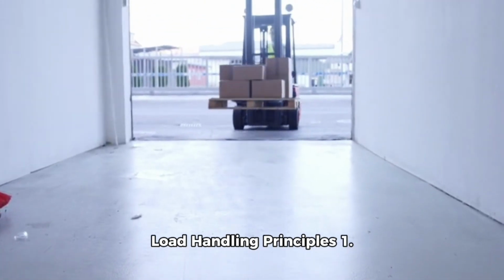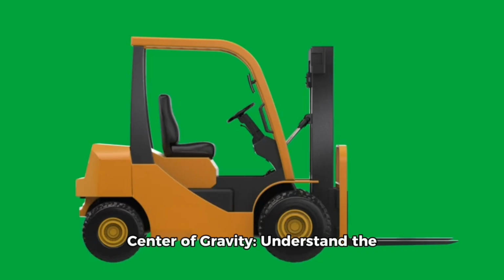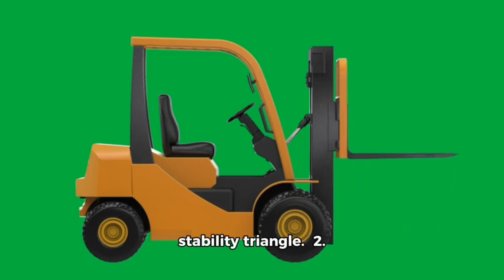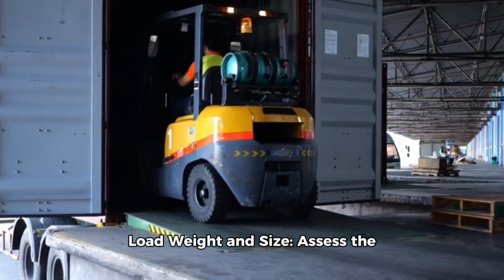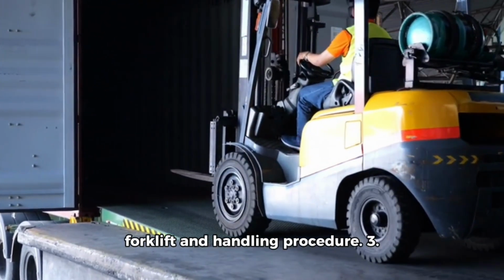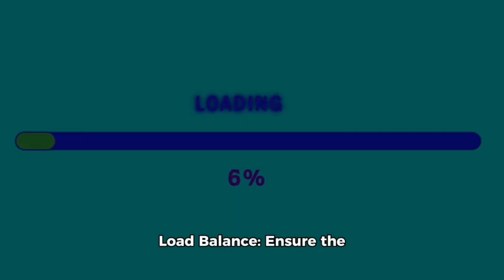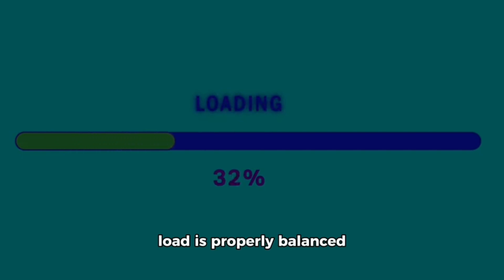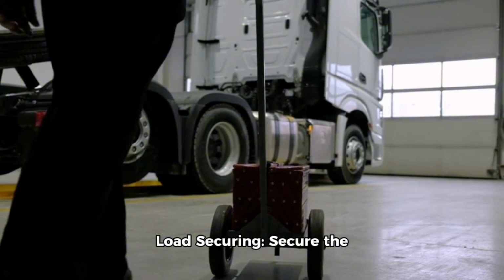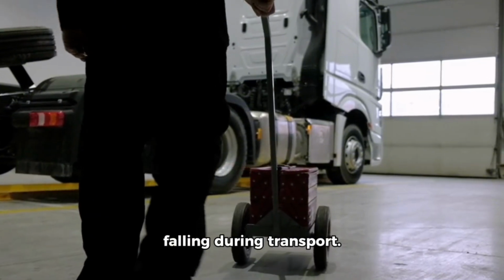Load handling principles. 1. Center of gravity. Understand the center of gravity of the load and ensure it's within the forklift stability triangle. 2. Load weight and size. Assess the load's weight and size to determine the appropriate forklift and handling procedure. 3. Load balance. Ensure the load is properly balanced on the forks to prevent tipping or falling. 4. Load securing. Secure the load to prevent shifting or falling during transport.